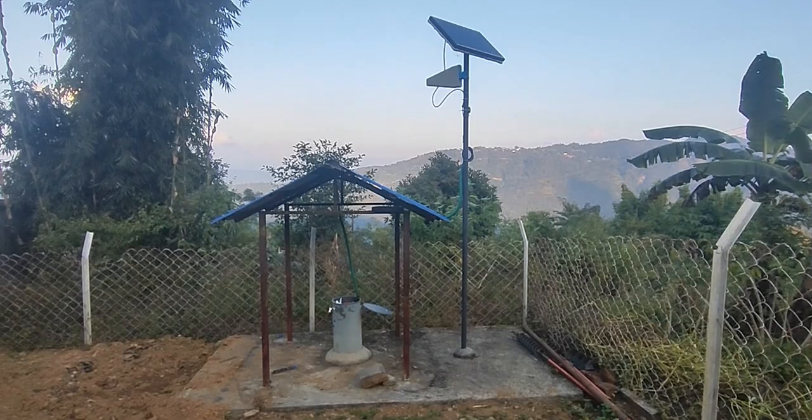And especially in weather, lightning should be avoided more, because lightning will damage all the solar panels and all. So you should make sure that that particular study area is having minimum lightning. And also the geology, which is very important, because it is well known that sensors on soft soil will give more noise than sensors on the solid rock. So generally what we do is we avoid the soft soils.